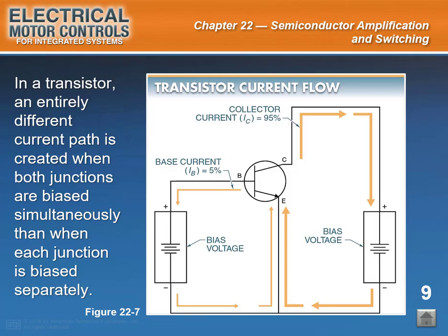across the forward-biased base to emitter junction, across which the strength of the input signal freely causes injection of current carriers, either electrons or holes, into the base region of the transistor. Because the base is both thin and lightly doped, not many of the injected carriers make it through the base as emitter base current, the rest are left in the base region.